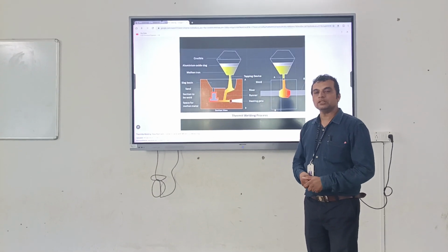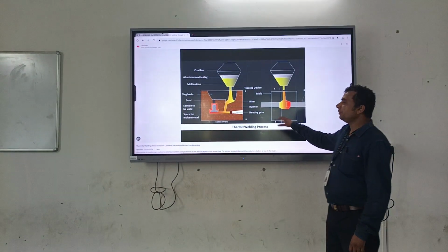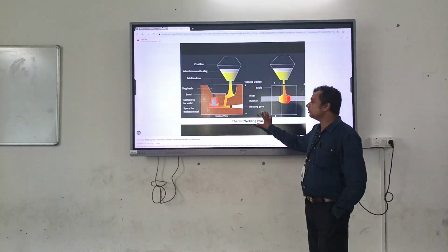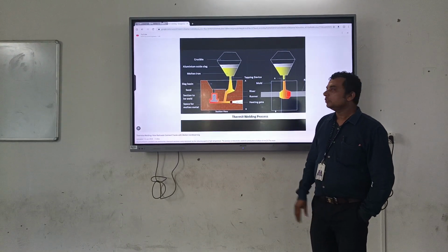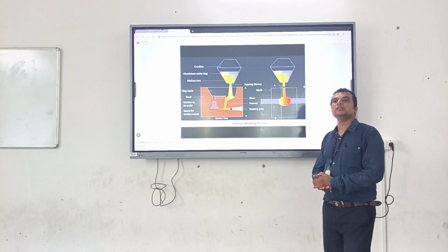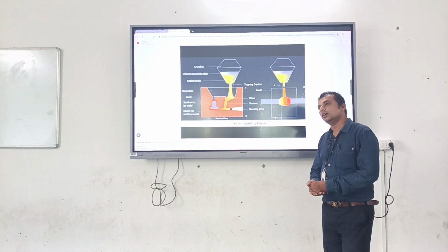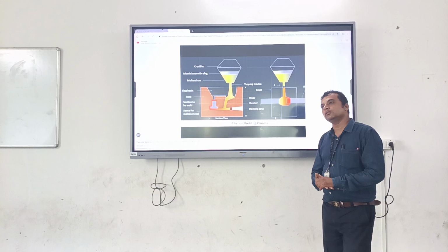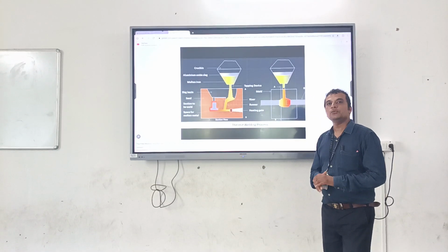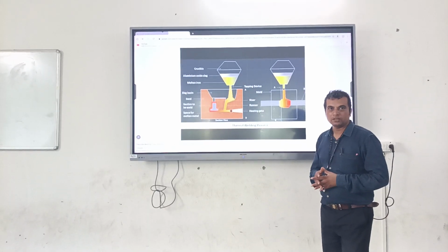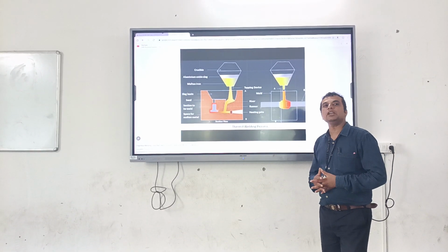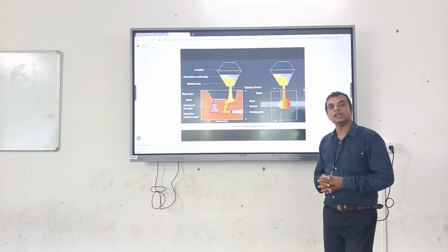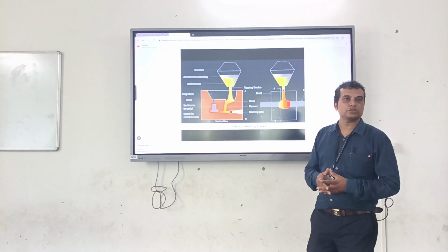Considering this definition, in this non-pressure type thermit welding process, we use the concept of heat without using pressure. We use it for welding large, thick metal rods or heavy, thick objects. That's why we use the thermit welding process. We use thermit welding for joining two broken railway tracks.